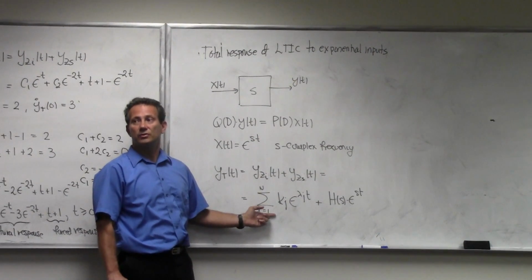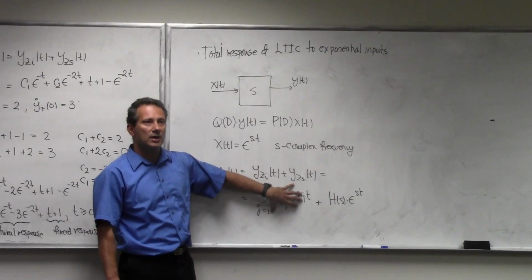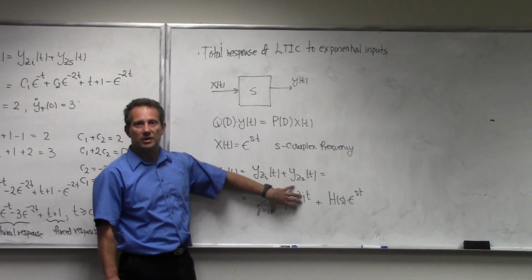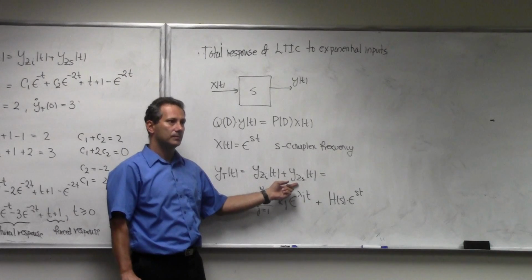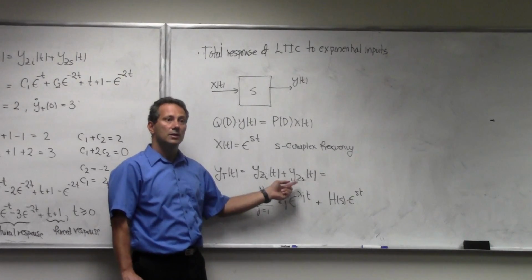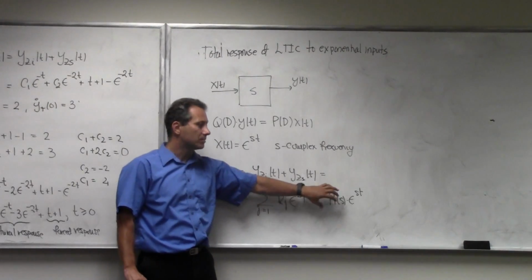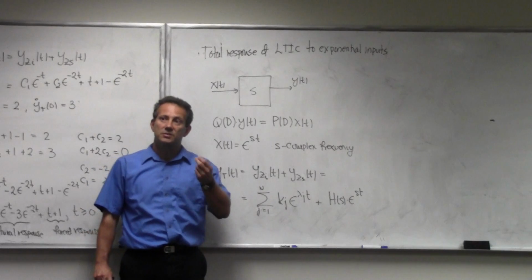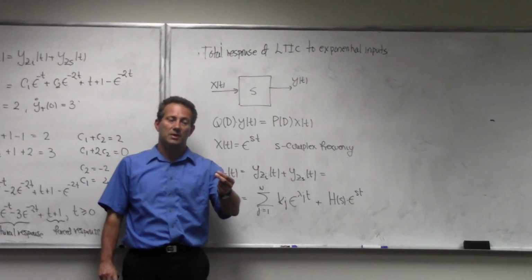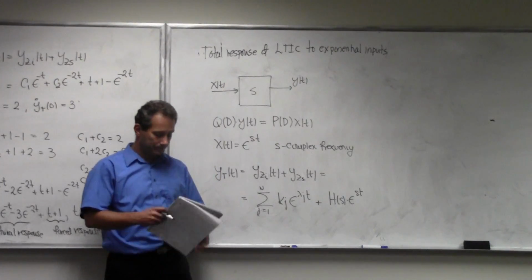If the system is responding to initial conditions, it has no choice but just to produce an output that is a linear combination of characteristic modes. What we learned last time is that if you have zero state and you present the exponential, the output of the linear system is also exponential, multiplied by some constant, which we denoted here as H of s. So exponential is a special kind of function. When you present exponential to a linear system, what comes out is pure exponential.